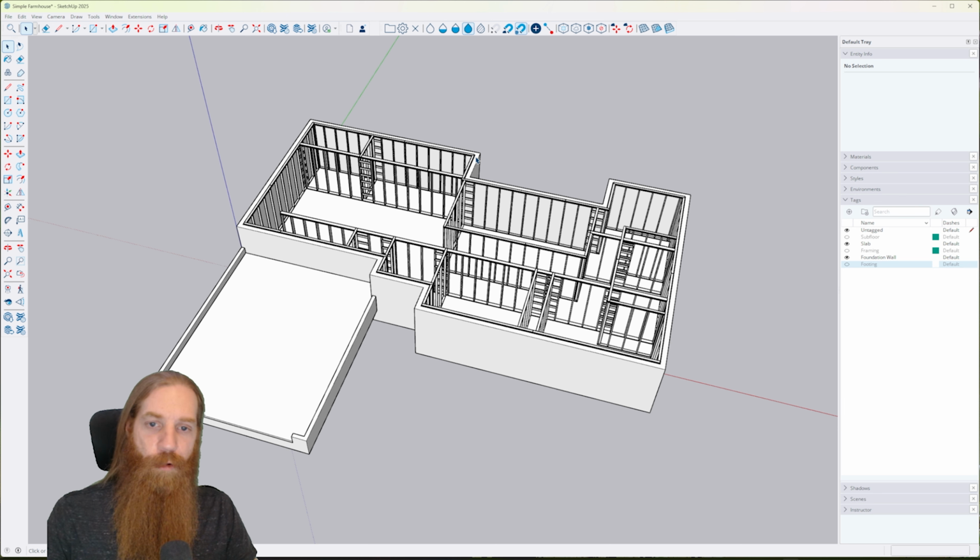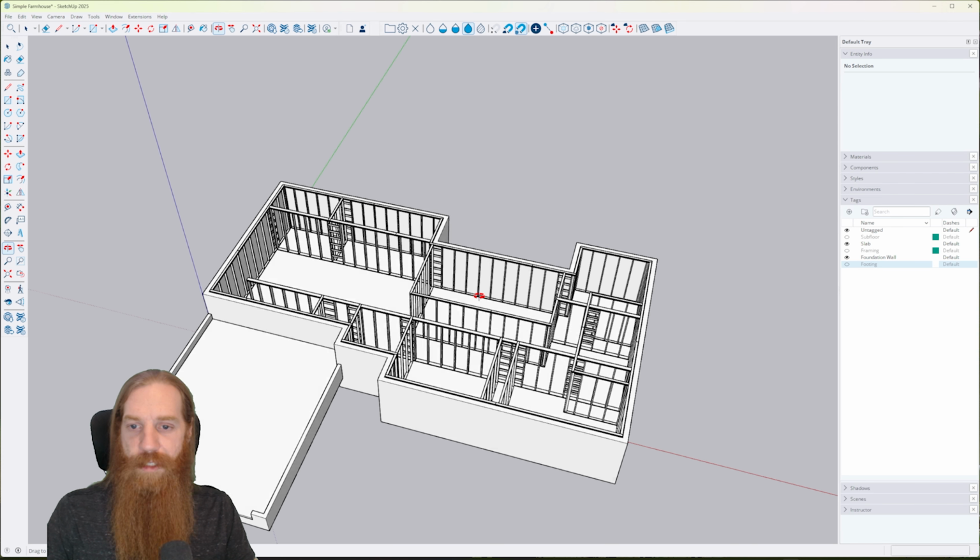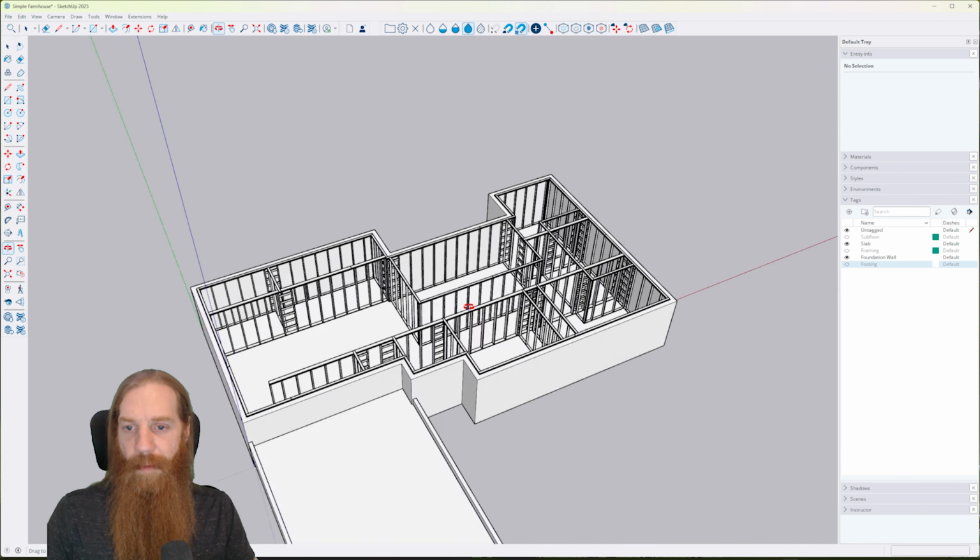I would just add a little bit of overage for scrap, bad boards. Every once in a while, you'll get a few boards in your studs that just aren't usable, right? When you order lumber, not every single board is going to be usable. Some of them are going to be twisted really bad or have a big crack in them or whatever. So you always want to order a little bit extra. But in this case, we'll be able to get real close to the exact quantity that we need, and then just add that little bit of extra on top, which will be really nice.